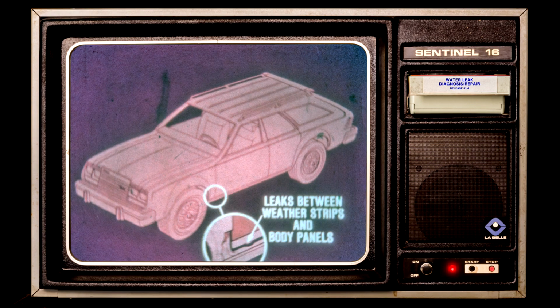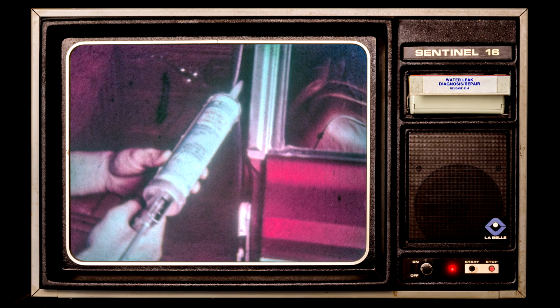If you locate a leak between a weather strip and a body panel, and the weather strip doesn't need to be replaced, a sealing operation is in order. There are 3 recommended sealants you can use. Both Kent Industries and 3M make bedding and glazing compounds that are well suited for this application. These sealants remain permanently soft to work in conjunction with pliable weather strips. They also have non-sag characteristics which make them ideal for vertical and overhead applications.